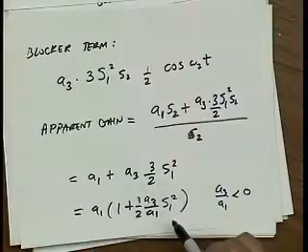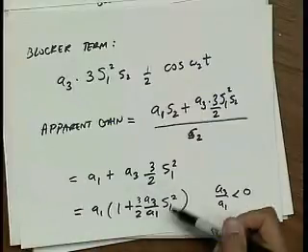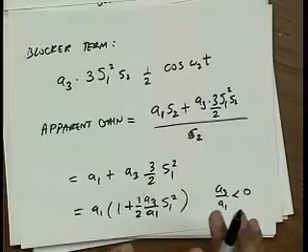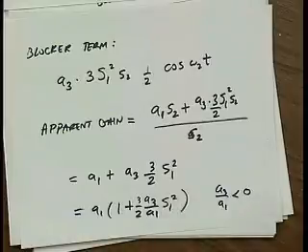And the amount of reduction depends on how strong the blocker is, right? Even if I have a really good filter at the output to get rid of all the intermodulation terms, even if that were theoretically possible, I still will experience less gain. This is the concept of jamming, okay? Any questions about this?